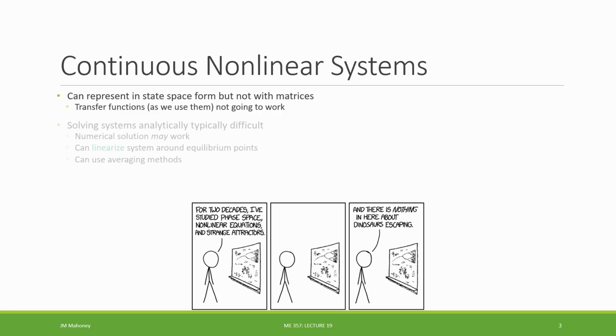Now, the analysis methods that we talked about in Unit 2 are not going to work typically for nonlinear systems. So those analytic methods for knowing what's the overshoot, things like that, are not going to work out for us. We're going to rely for this section, for this course, just on numerical solutions using typically ODE45. And for many nonlinear systems, a solver like this is going to work, either ODE45 or ODE23, depending on the makeup of the system.